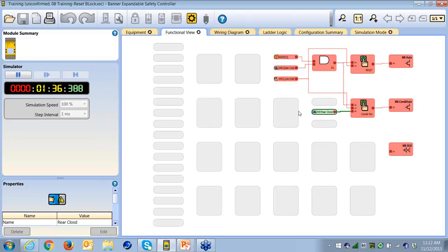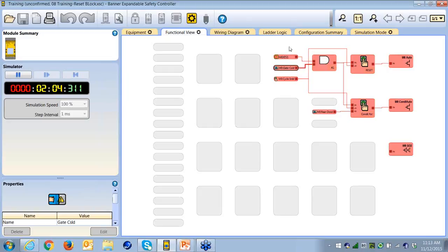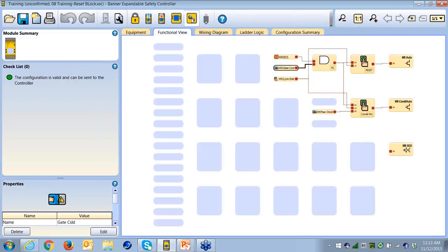So you wire that into either hardwire or through logic in the reset enable. And now when the input goes true and I push the reset button, happen to use the same reset button twice, this turns on. I can lose that and still continue to stay on because all this guy does is enable the latching function to occur. It does not reset the latching function as the in variable does.